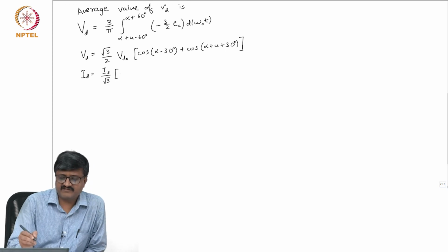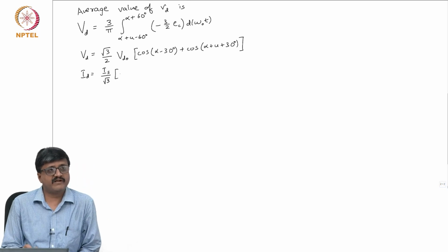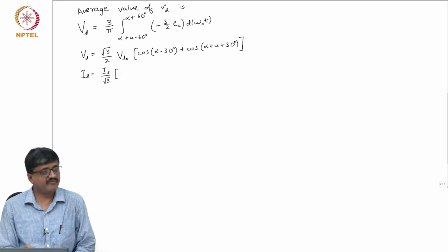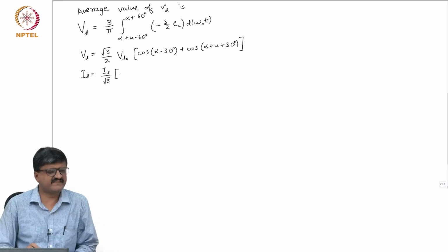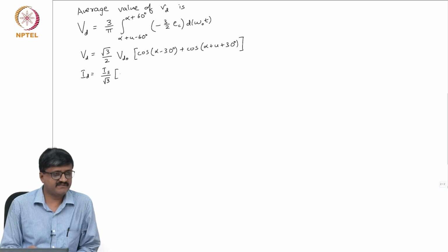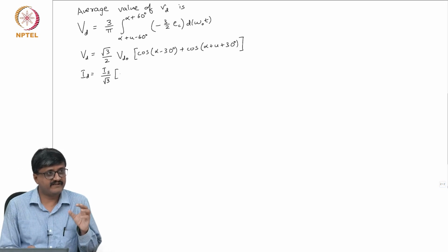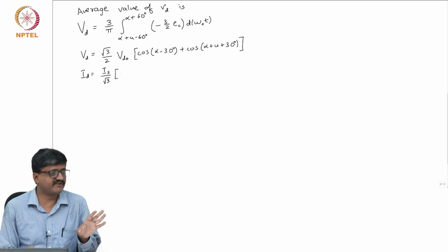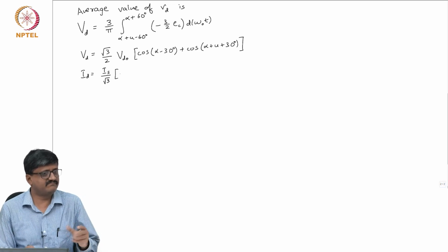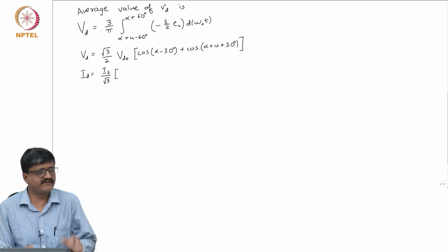By the way, I just want to let you know, whatever I have asked you to do so far are all simple ones, except the expressions for the fundamental and harmonic component for the DC side voltage and the AC side current in the case of 2 and 3 valve conduction mode. So only those are laborious. All others can be done in just a few minutes.